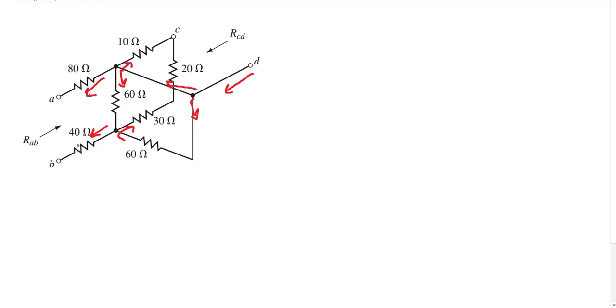So practically, for an ohm meter put here in RDC, this one and this one are cancelled. They are not included in our circuit. The rest are included. Now, since the rest are included, we have to use our imagination a little bit and redraw this circuit to become easier to look at.